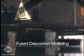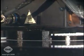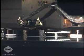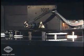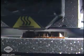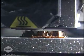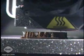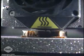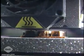Fused deposition modeling involves feeding a thermoplastic filament into a heated extrusion head that moves in the X and Y axes. The heated extrusion head melts and deposits the thermoplastic material on a table that moves in the Z-axis, building the model. The molten thermoplastic is channeled through an extrusion tip, which reduces it to a fine bead for deposition onto a substrate material. After depositing each bead, the tip flattens it in preparation for subsequent layers, and the model is built up layer by layer.